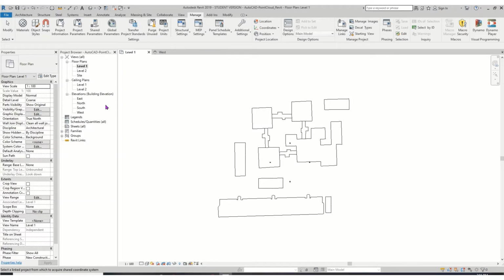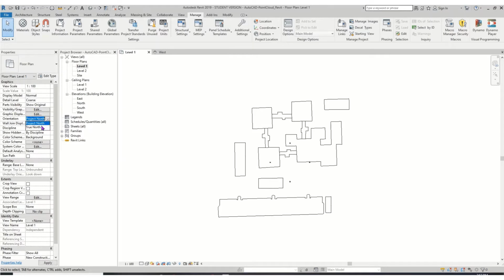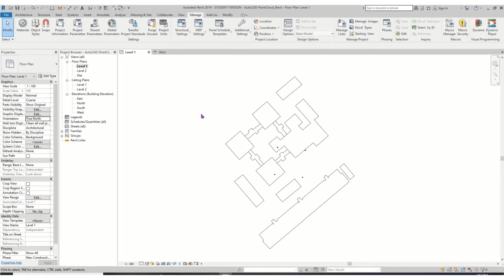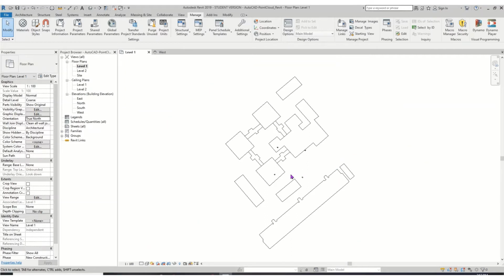We have two ways to check. First, we can check the project north. Each time you choose, for example, project north, you click here, nothing. Then we choose true north, click. So it's not quite automatic, you just need to click, at least the first time. This shows that you have successfully brought in some coordinates from the incoming CAD file.